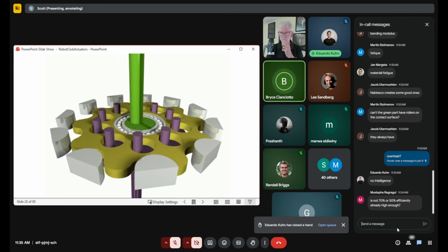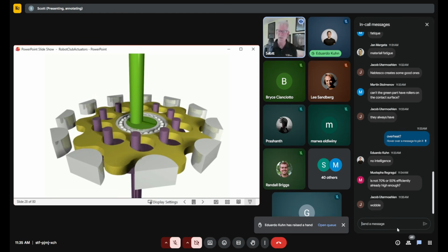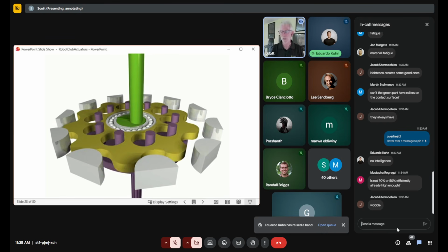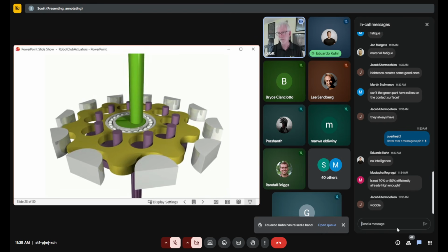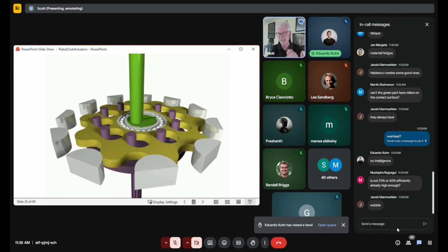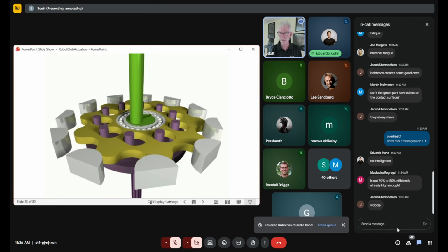It's going to cause vibration. Yes. Anyone that's had the overload on their spin cycle knows exactly what that is. And the way you solve it is you make two stages. You have one on the other side that's offset from it, and then they kind of cancel out, so you don't get the vibrations and everything else. So there are ways of being able to solve it, and usually cycloidal drives are like that.